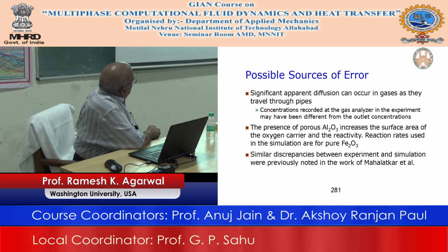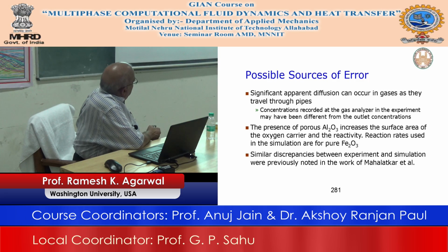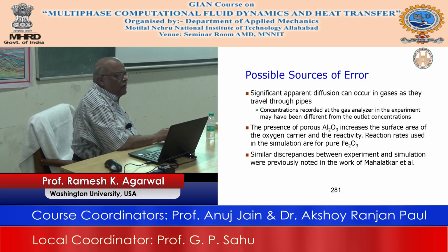So what you have is the collision. That is important, because there is collision with the walls and collision among the particles. Again, you can have elastic collision, inelastic collision, this and that, but just keep it simple, and that's good enough. Then there is the gravitational or buoyancy force, which becomes important because fluidization is going on. And here is the drag force, which is very important, and people are still doing research on that. This is the difference between the fluid velocity and the particle velocity, and there are all kinds of formulas for it.